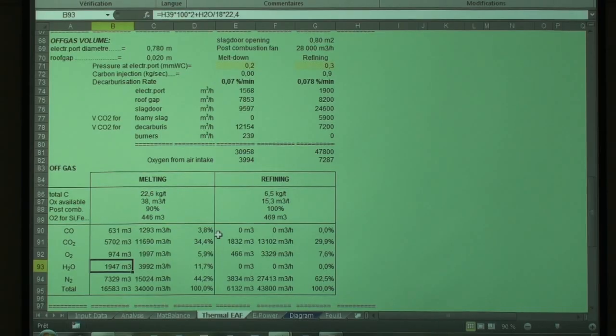So why I have in mind to use oxygen for the post-combustion: we blow only a small amount of oxygen through the runner, and the oxygen can react in the upper side because of the baghouse filter suction. So they make more high-speed combustion, post-combustion. It is one of my study points.